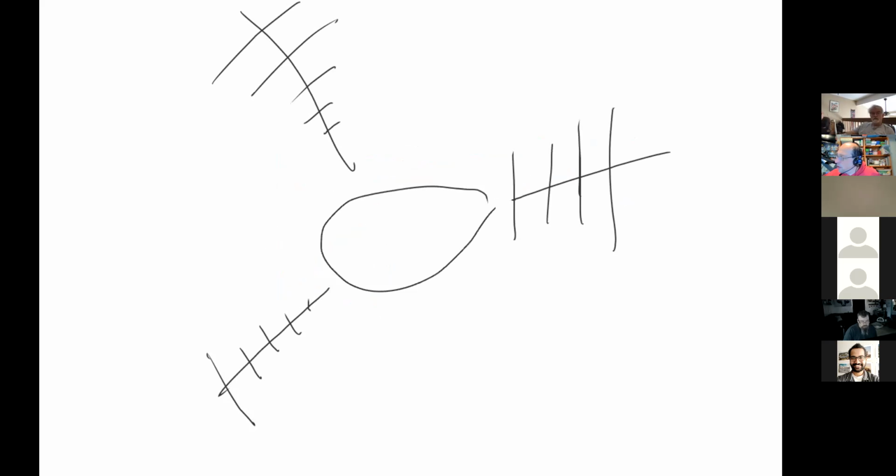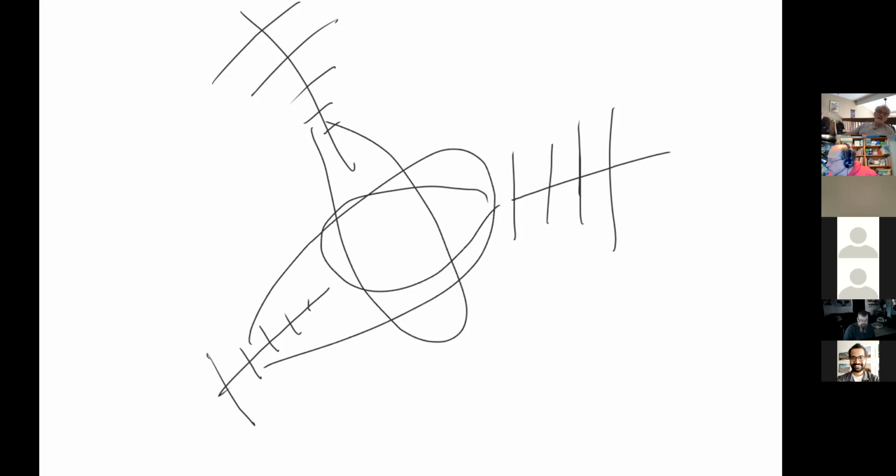Which of the following methods is used to locate sources of noise interference or jamming? That would be direction finding. Typically what we do is we take an antenna here, an antenna here, and an antenna here. You can do it with one, but it's a lot easier with multiple people. You say, okay, it's somewhere in this area, and this area, and this area. Here's my intersection point. We're looking somewhere in here. That's how the FCC does triangulation on interfering stations.